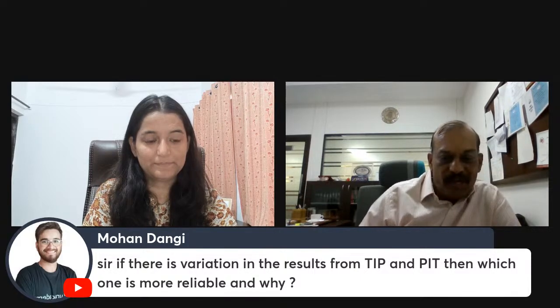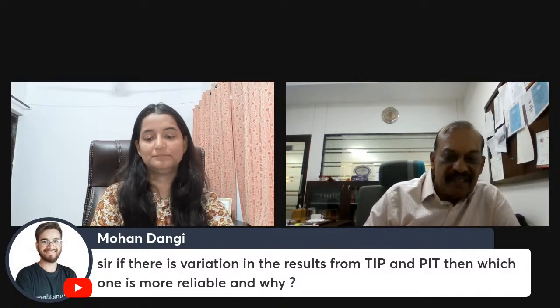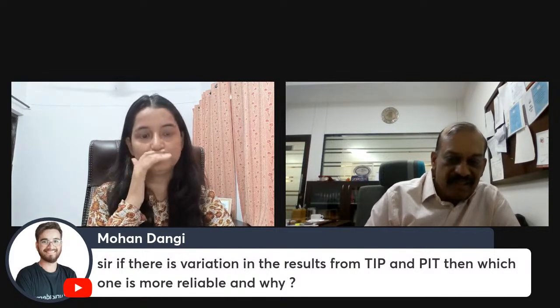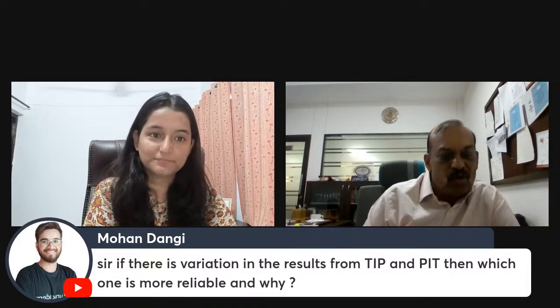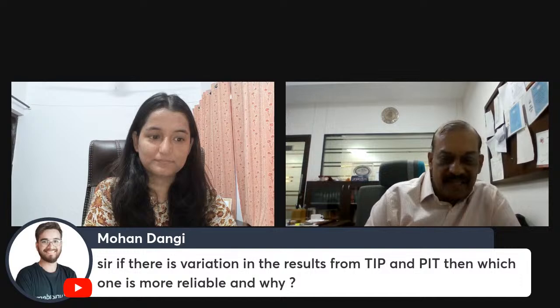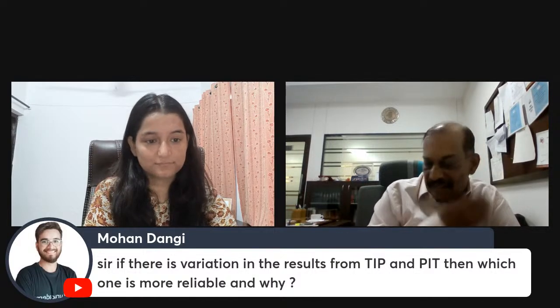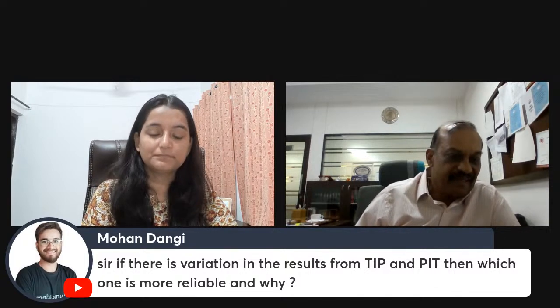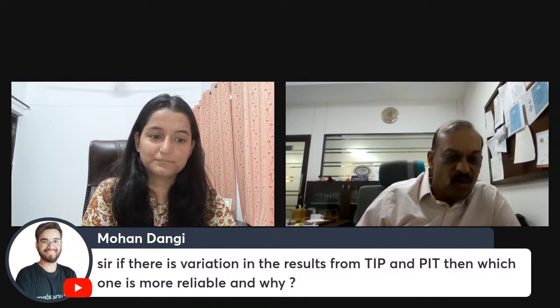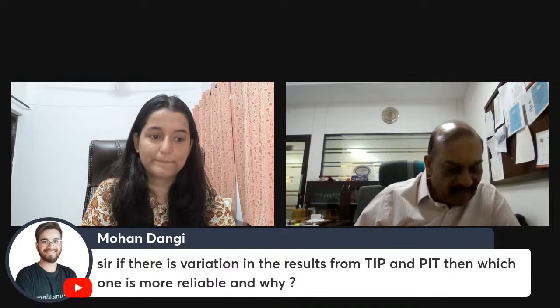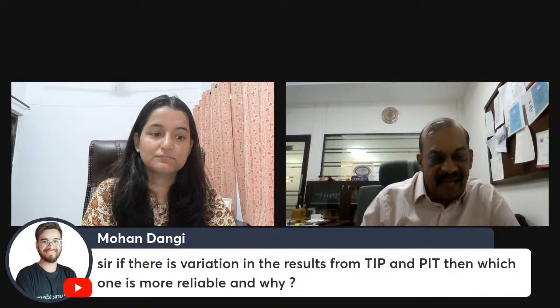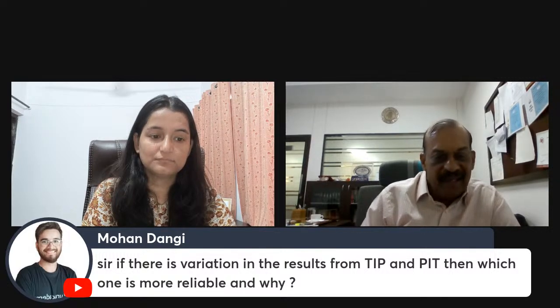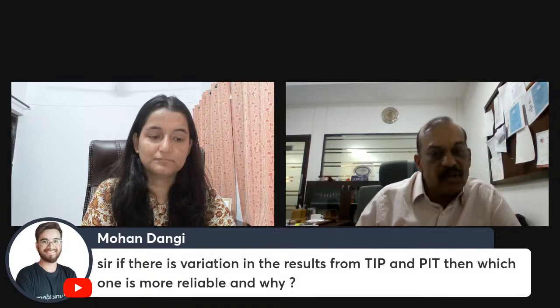As far as which one is better, it is tough to answer. If either of them shows a defective pile, it needs to be investigated properly. In fact, the equipment manufacturers of TIP claim that TIP is more reliable. But ultimately, the proof is in the actual pile, checking out the pile. If you find a defect, you need to investigate it.